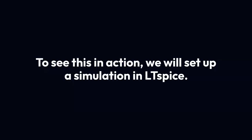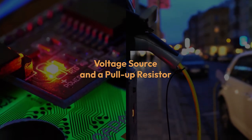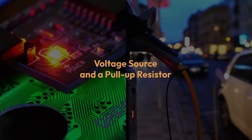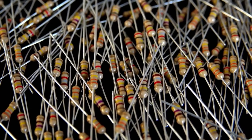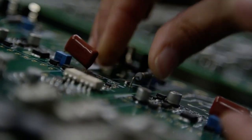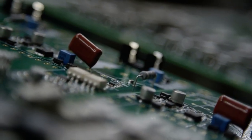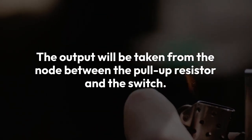To see this in action, we will set up a simulation in LTspice. First, we need a simple circuit. We will use a voltage source, representing our power supply, and a pull-up resistor. This resistor ensures our output is held high when the button is not pressed. Then, we will connect a switch to ground. This switch will simulate our push button. The output will be taken from the node between the pull-up resistor and the switch.